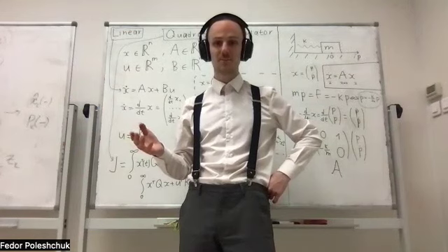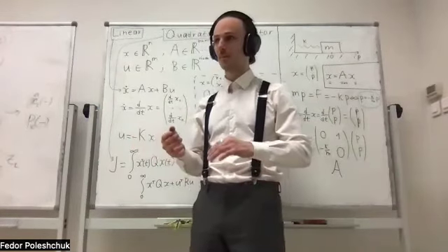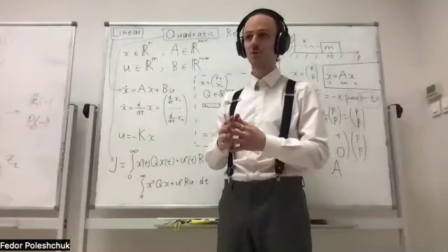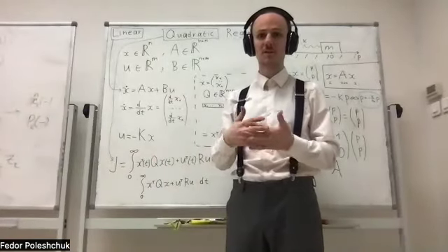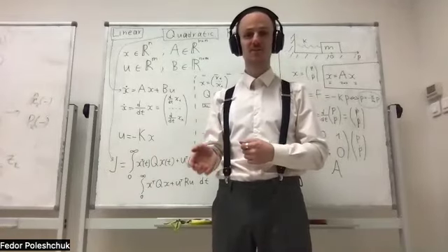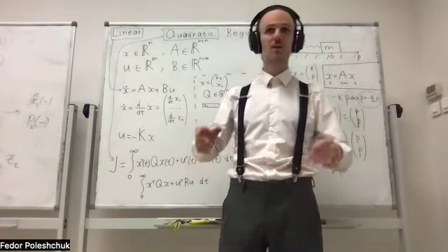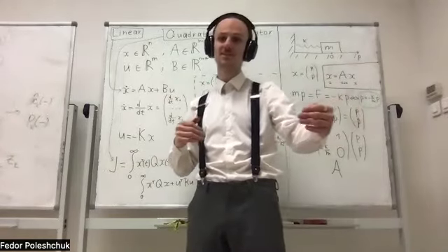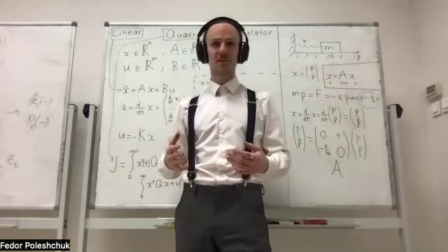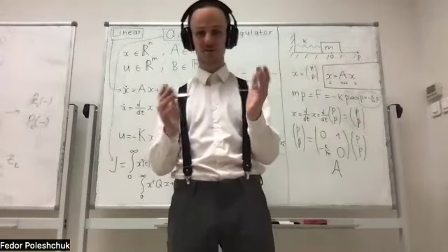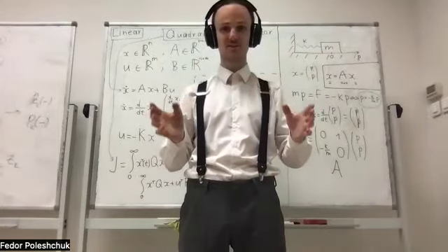Let alone the fact that the noises will, because of the butterfly effect, lead to our system approaching different state. So we can go along with a much simpler part of the state, like X, Y, and theta. And this is exactly what is used. So in the scale of the field and in the scale of seconds and tenths of seconds, our robot is described as a system with only 3 coordinates, with no velocities. So the whole state vector is X, Y, and theta, and that's enough.